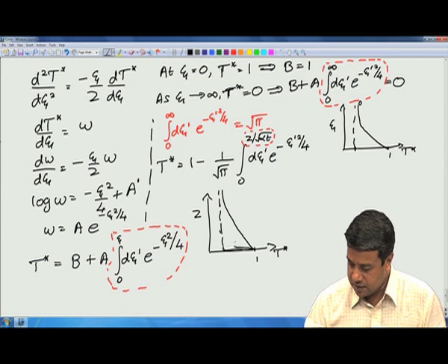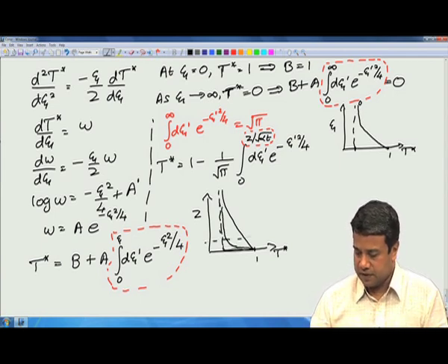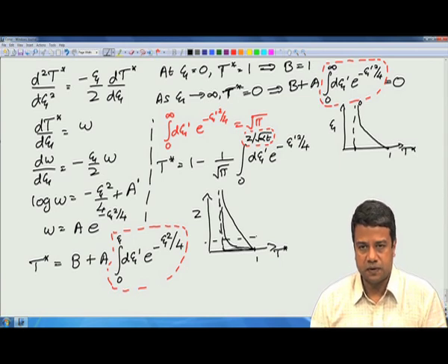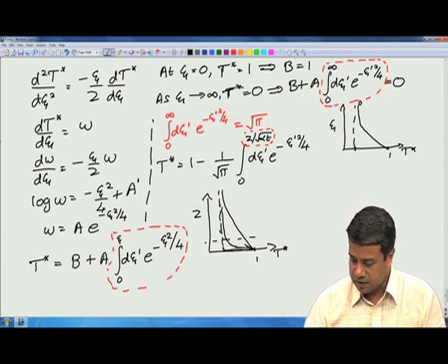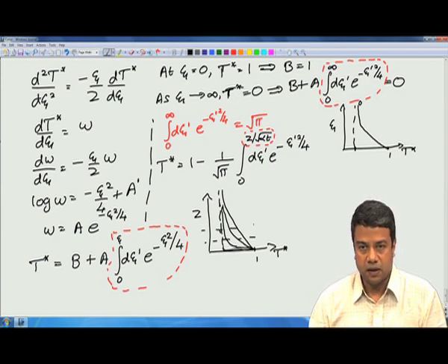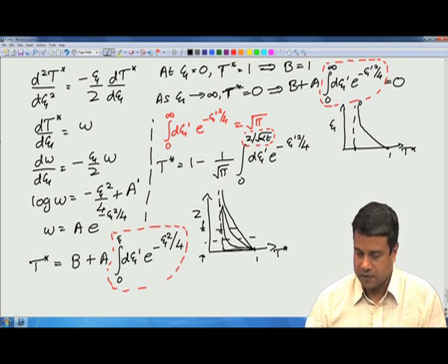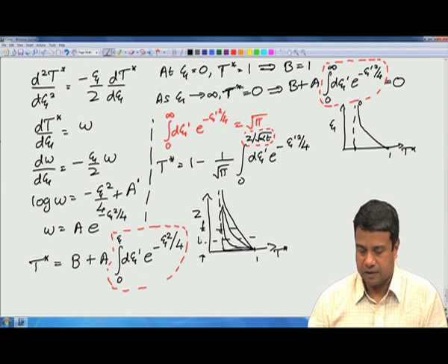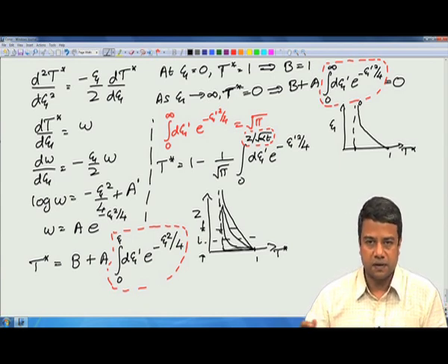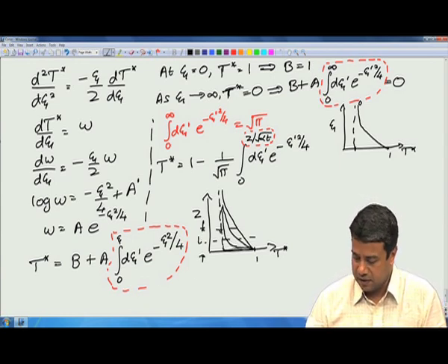Then as time progresses, the depth over which this temperature field penetrates would be small. And then as time further progresses, this would increase and increase further. How does it increase? It is obvious from this functional form. This penetration depth of the temperature field, this length scale L over which the temperature has penetrated, L has obviously got to be proportional to square root of alpha t.